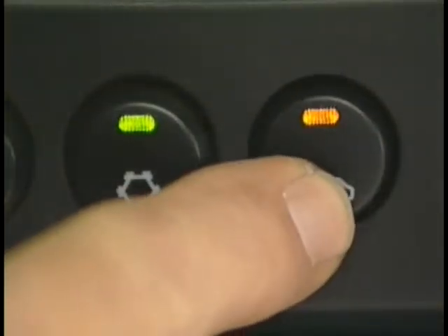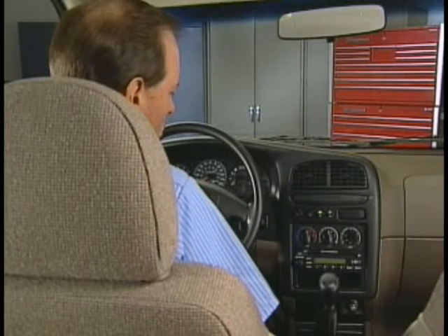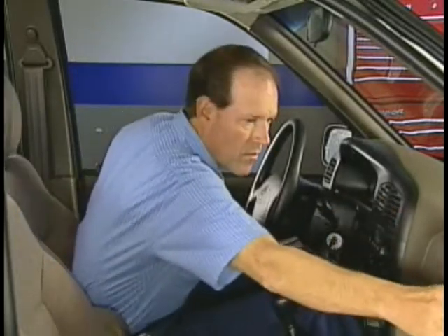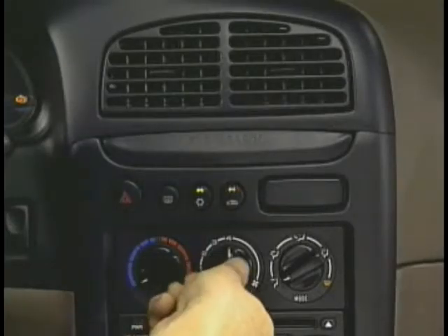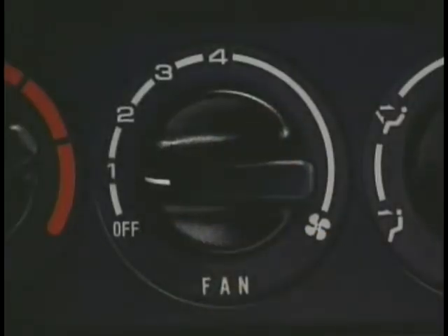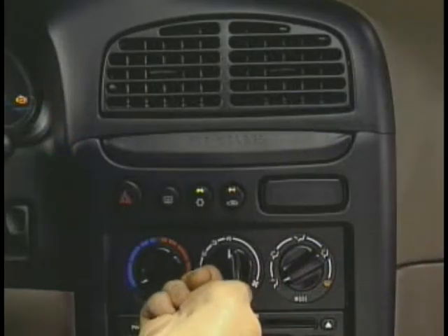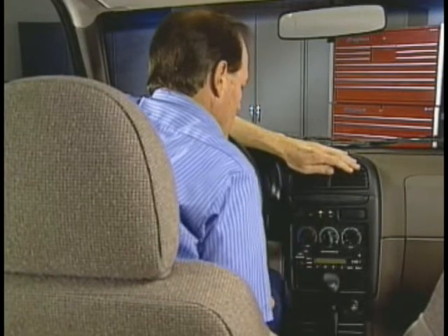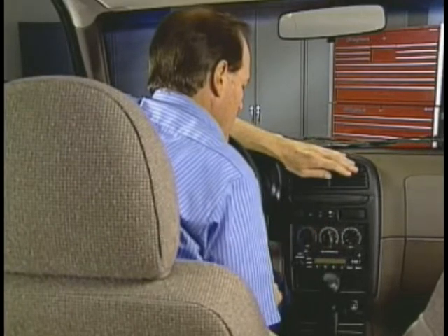Engage the recirculation or max mode and listen for a change in blower motor operation and for increased airflow. The electrical circuits will have to be checked if there is no change. Then put the air conditioning system in the normal mode and change the blower motor speeds through all positions. Blower motors that work on high speed only will likely have a failed resistor block. The general diagnosis should conclude with a check for unusual odors. A sweet smell indicates a coolant leak from the heater core, while a strong musty odor indicates a clogged evaporator drain or a bacterial coating on the evaporator fins.